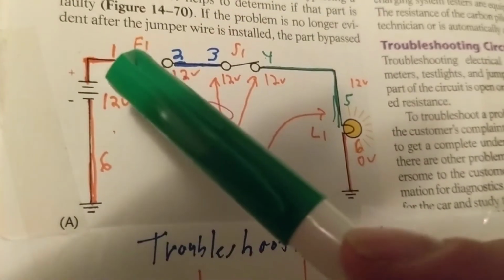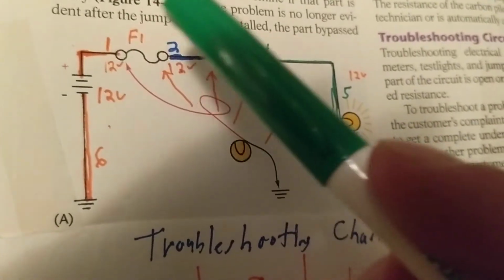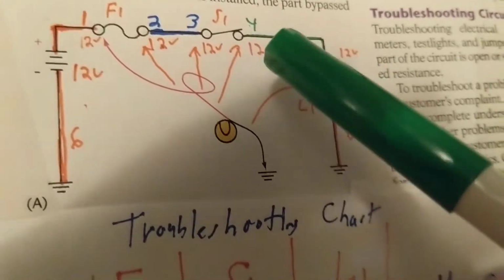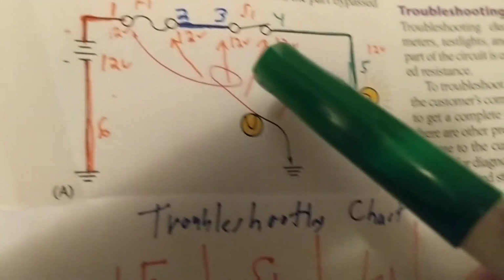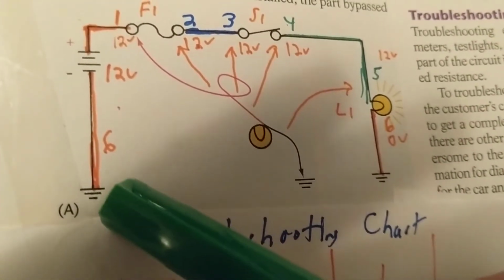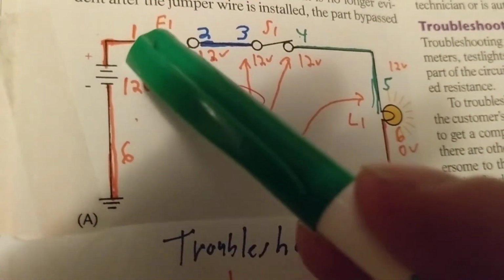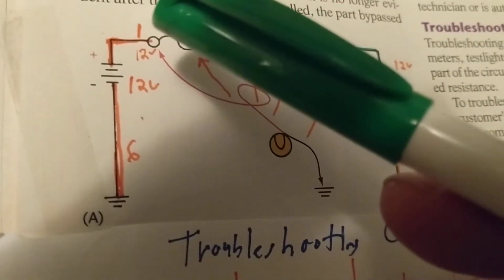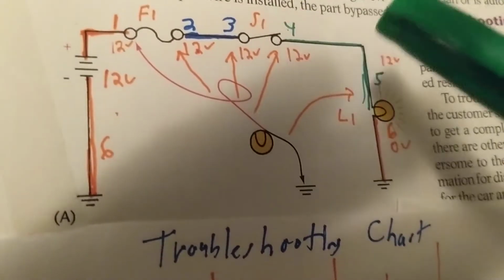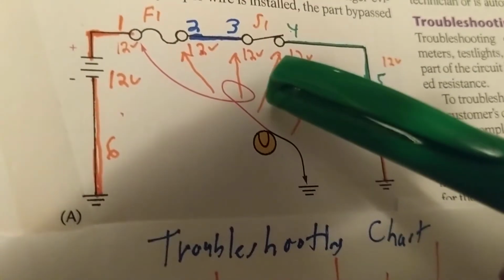I can also take my voltmeter and measure across. I could take the positive here, put the negative here. I could take the positive here and take the negative here. But that is too tedious, and the easiest way to do it is to leave one lead as a negative, just like in automotive. You always leave the lead to ground, and you move around the positive. So this is the positive lead, right? I move the positive here, here, here, until I get to the point that I want to measure my voltage.